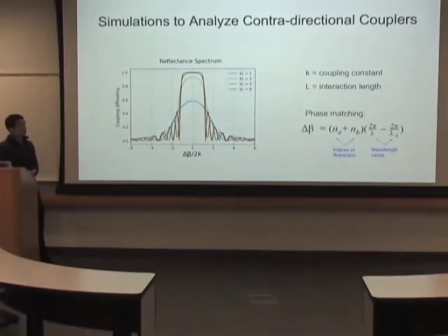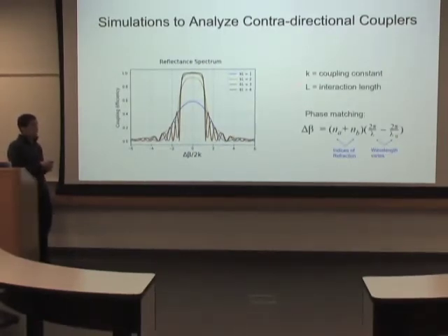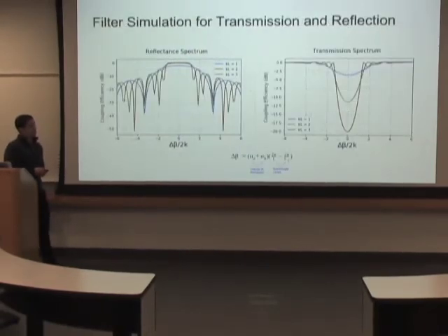Another very important aspect of my internship was optical testing, where I would test the contradirectional couplers on a chip that some grad students on the team I was working under designed. It contains a lot of test structures, and my job is to measure them. The overall question I was examining is, how do physical parameters such as grating length affect the wavelength spectrum? So this is my setup for testing the filters. What you're seeing here is the waveguides and the ports that go into the grating, which isn't pictured, but it's very small and hard to discern from a picture like this.